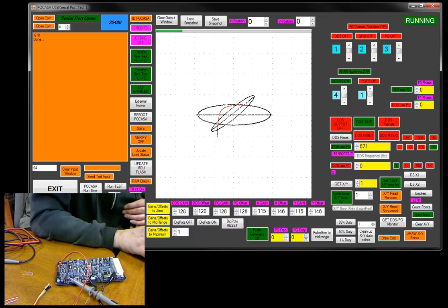Down here I got a pulse generator. If you're ever shooting a transistor, or let's just go with a MOSFET, you can put your drain and your source across the two probes there. And I got a pulse generator output that you can set using these down here, and your gain and your offset for your output for triggering your gate. And you can watch it when it's totally off.